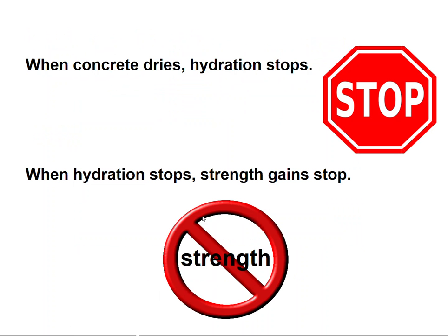So when concrete dries, hydration stops. And when hydration stops, your strength gains stop as well. So the longer you can keep that moisture present and liquid, the more strength you're going to get out of your concrete.